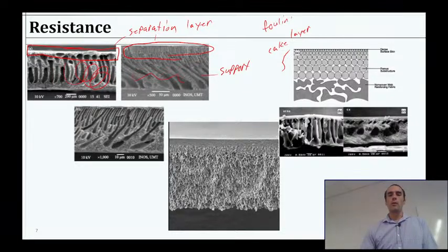So we call it fouling when the membrane gets dirty. We often have lots of procedures, maybe physically cleaning, maybe physically shaking, scouring it with bubbles, backwashing it, eventually dunking it in acid or bleach or something. Lots of ways to try to get rid of that fouling.